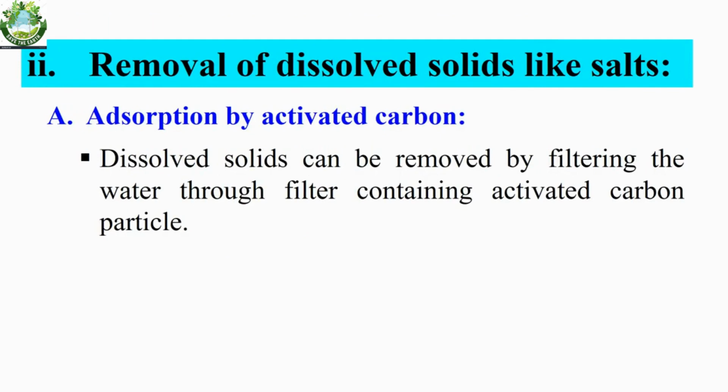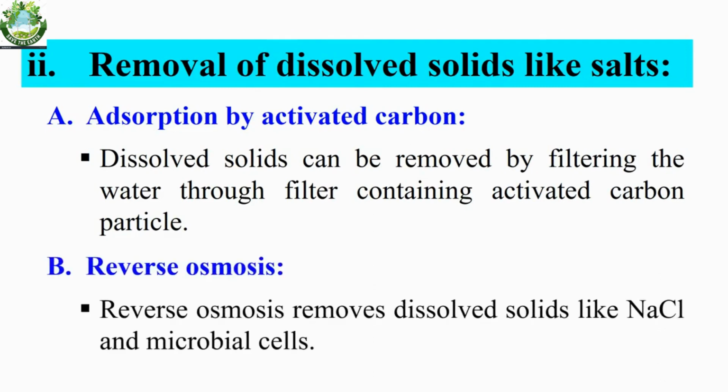Next is the removal of dissolved solids like salts. Various techniques can be used, like adsorption by activated charcoal. Here the dissolved solids can be removed by filtering the water through a filter containing activated carbon particles. And sometimes we can also use the technique of reverse osmosis for the removal of dissolved solids.